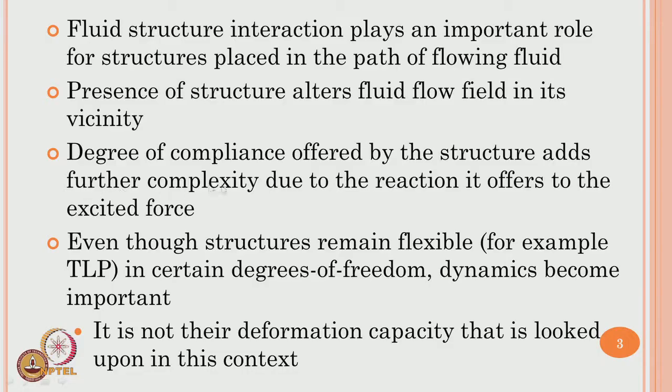Adding to it, the degree of compliance offered with the structure, because the degree of compliance is nothing but the support conditions given to the system by the external boundaries. For example, it can be floating and anchored to the seabed, it can be completely floating and controlled by a DPS system, can be rigidly fixed to the seabed, etc. So, what is the boundary effect you are giving to the structural system to avoid the degree of compliance or to induce a degree of compliance adds further complexity, because this will create additional reaction forces to the excited force.